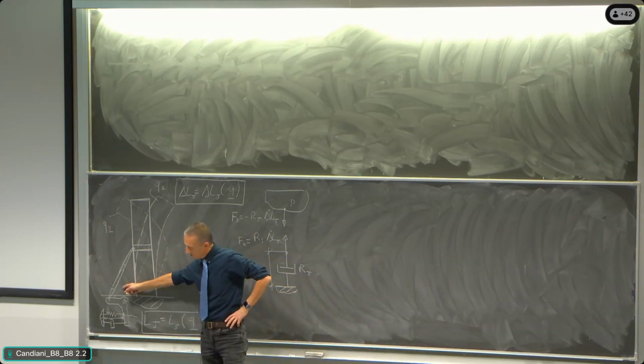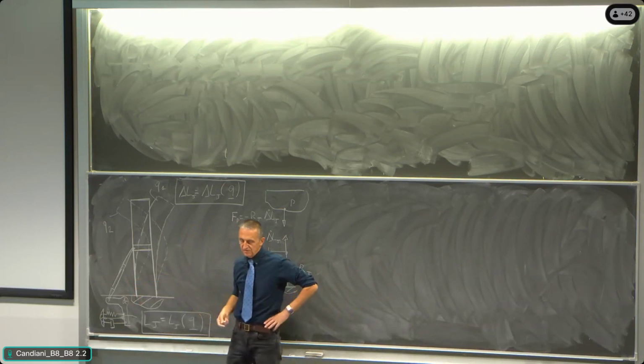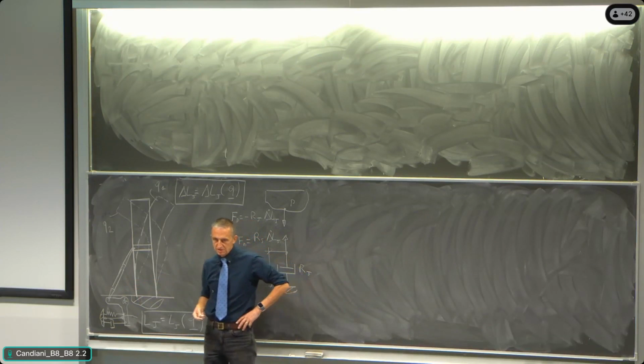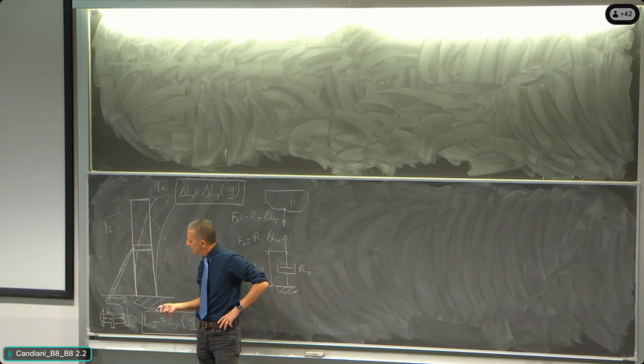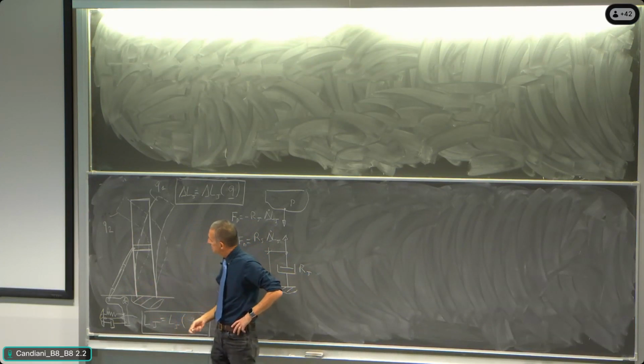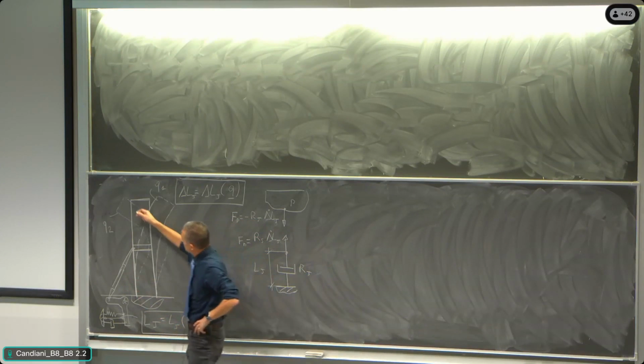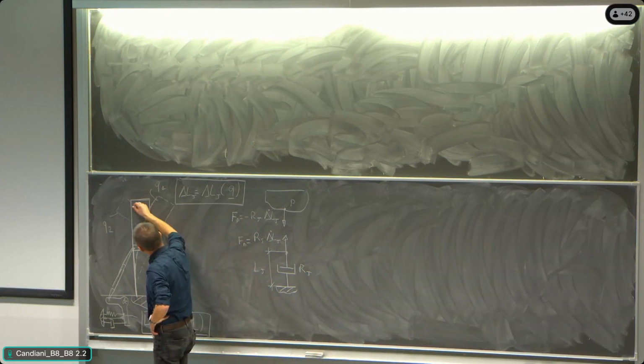So the legs of the Isozaki now have the purpose of damping the motion of the building due to the wind. There is also another option. Usually there are no buildings around the world with devices like that. Usually what is happening is that on the top of the building there is a mass, and this mass can move, or more than one mass.